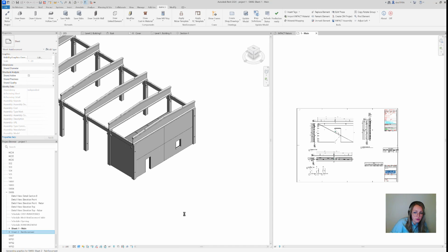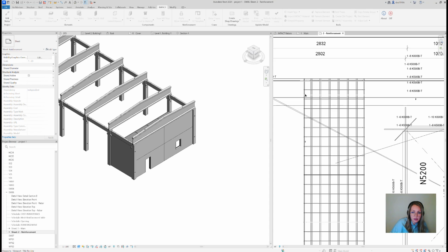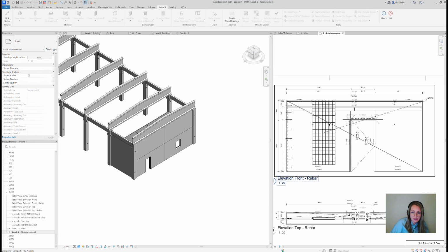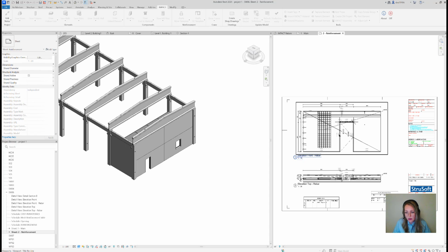If you open the reinforcement, what we can see is that you remember we drew this bended mesh, right? So everything that you see in the reinforcement on the main sheet, I have predefined as a user, how and what to dimension on each particular sheet, each particular view. Shop drawing templates are a very powerful tool, and I think it's a time saver, especially when you do precast.